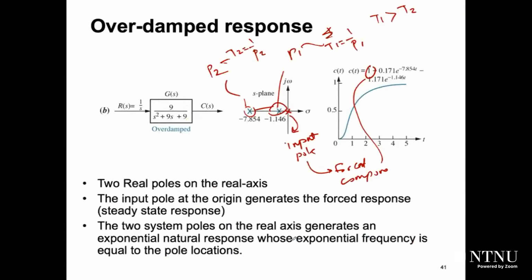So anyway, we can say that this overdamped response looks like a response of a first order system, but you will discover it if you do a step response. When you see this bulge here, it will let you know that this response is a second order and it's not a first order. If it is first order, it will be clearly like this one.